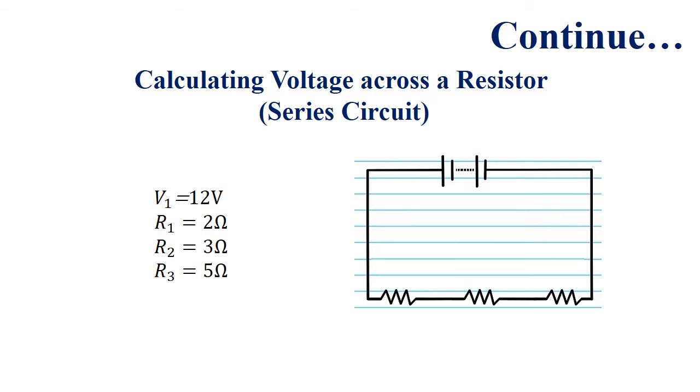Understanding a series circuit. A series circuit is easy to identify. It just has one loop of wire with everything arranged in a row. The current flows around the entire loop, going through each resistance or element in order. The current is always the same at any point along the circuit, while the voltage across each resistor will vary in the series circuit. So here we have our circuit consisting of one battery and 3 resistances.